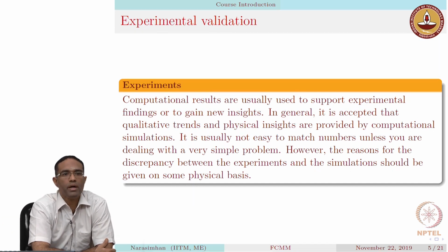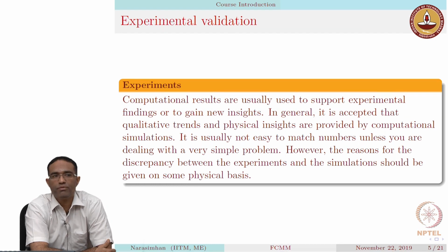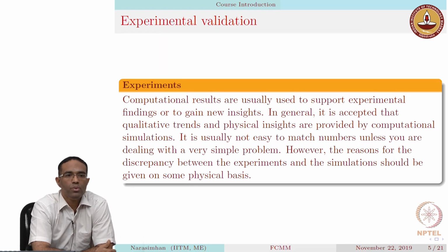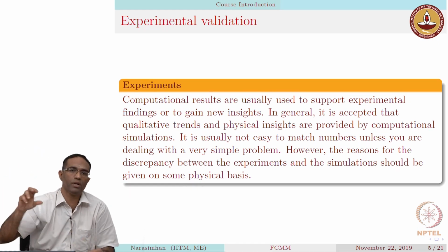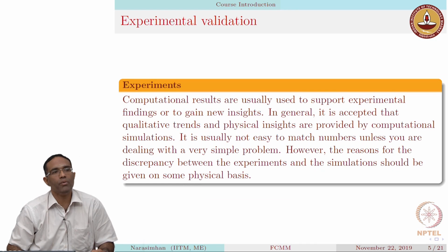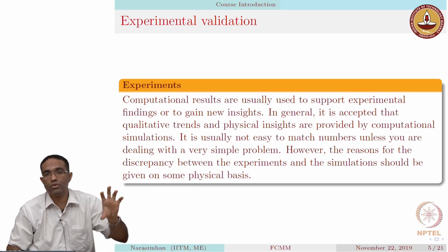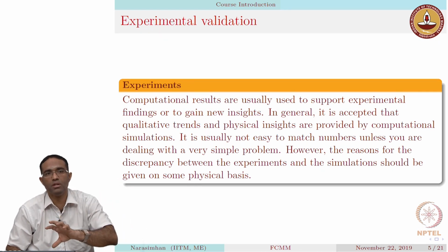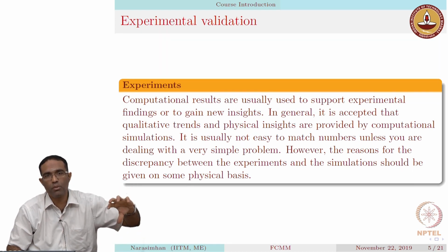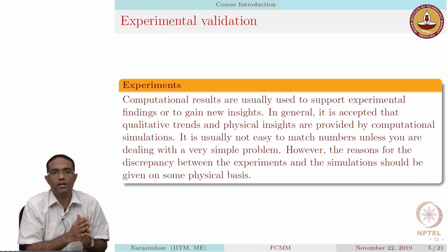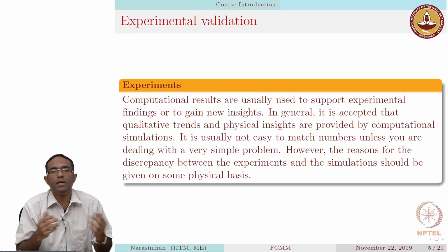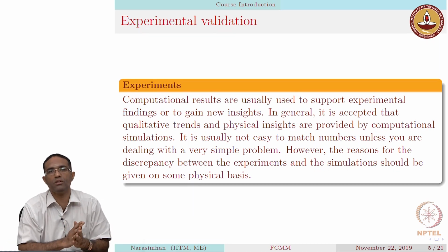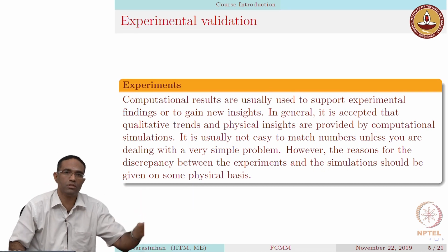For example, when you are trying to calculate the elastic properties of copper, you generally perform the experiments with a dog bone specimen, which is going to consist of a large number of polycrystalline grains. However, when you try to match these results with simulations performed on a single crystal copper, you don't expect the same kind of values in both. You should be able to logically conclude that one consists of a large number of grains, whereas the other consists of a single crystal.